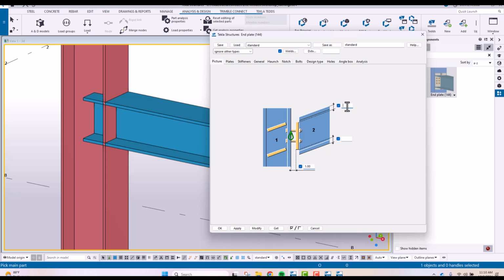And then here, if you notice, I put 50 and 40. So meaning the extension of my plate will be 90 from the top of the steel. So I will put here maybe negative 90, because if I put positive, then it will go down. I think this one is negative 90 if I'm not mistaken. If not, then later on we can remove the negative, because it's a matter of positive negative. So meaning the gusset plate will extend 90 millimeter from the top, 90 millimeter from the bottom. Okay? From the drawing in the board.